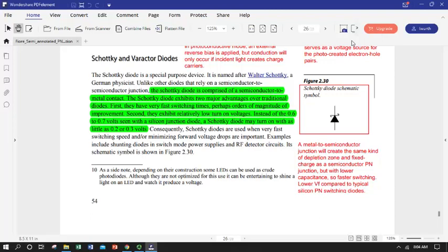So if you want to think about it, and I'm sure this would come up if you're extrapolating back, you effectively have a Schottky type junction at the connection points between your wire and any piece of doped semiconductor. And the way it works with a standard diode is the energy hills of those two regions are in opposite directions and cancel out. But if you just had one, you would have a Schottky diode.